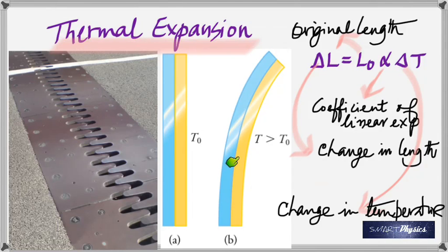Look at the diagram and tell me quickly which metal expands more. I mean, that's easy. The blue or the yellow. Which one expands? Which one has a higher coefficient of linear expansion? The blue one. Why? Because you can see that it's bending inwards because this one tries to have a greater length. And this one is definitely a little bit smaller when it bends that way, right?